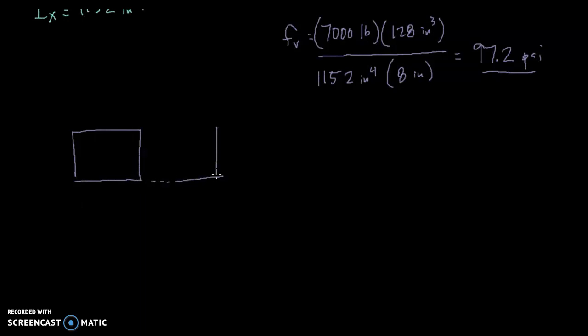In fact, we're looking at a beam from the side, and the bending stresses, if you'll recall, are at their maximum at the extreme fibers. We see maximum compression on top, maximum tension on the bottom, at least if it's loaded in the downward direction. What happens with the shear stress is that the profile for the shear actually looks something like this. It bows out towards the middle. And while the bending stress is 0 at the neutral axis, the shear stress is actually at its maximum at mid-plane, at the neutral axis.